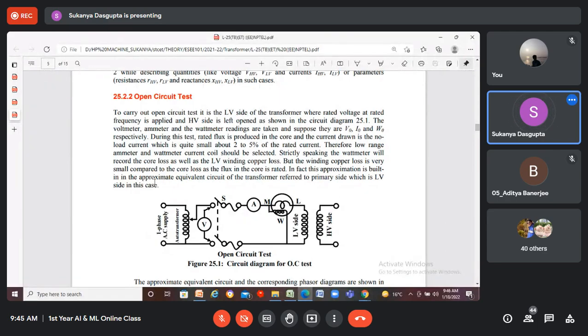In order to magnetize the core. Already you have learned why the core needs to be magnetized always, right? To satisfy the transformer operation smoothly, we need to confine constant flux within the core, right? Flux should not be varied within the core material. It should be kept constant, right? Otherwise, there will be a chance of reduction of primary as well as secondary induced EMF across the primary and secondary windings respectively, which in turn will affect the actual working of the transformer. Okay.